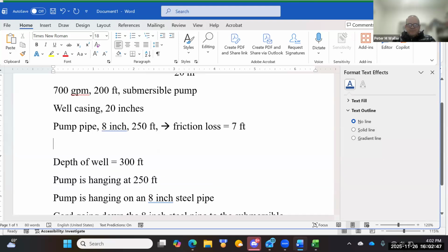So really, we need a pump. And also, I said that the discharge is to the atmosphere because we're just discharging to the reservoir. And so the discharge pressure equals 0. Or I could add like 10 feet if I think I'm going through some fittings. So 0 discharge pressure, but we might have 10 feet of losses in fittings.